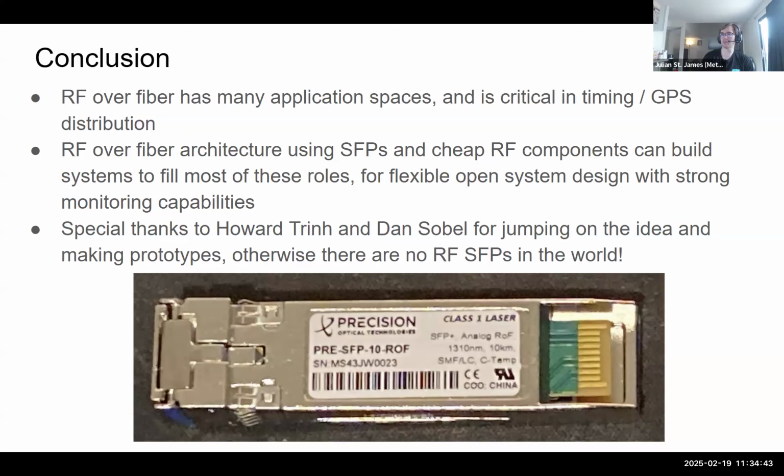I don't know, Dan or Mike, if you want to add anything. Sure, I'll just add a little bit on the standardization behind this. As Julian explained, these are standard transceivers with the digital electronics removed. So it's a pass-through design of a current product that we offer. The standard that they meet is SFF-8472.